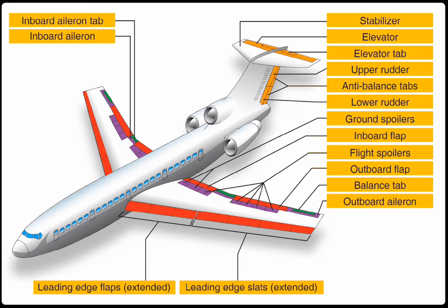How do wing flaps affect landing speed and approach angle of an aircraft? Flaps increase lift of the wing, so speed can decrease without decreasing lift. Permits a steeper glide angle and lower speed for landing approach.